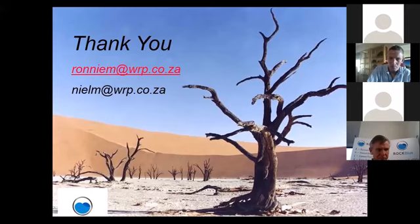Our next question for Ronnie is whether the nature of soil conditions can cause leakages. Definitely, absolutely. You will often find, especially in areas that have got clay, that the clay will move. During the dry season it will shrink a bit, and during the wet season it will expand, and that type of movement will create problems in any reticulation system.